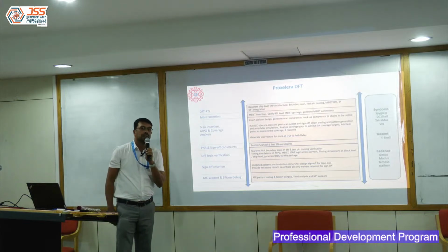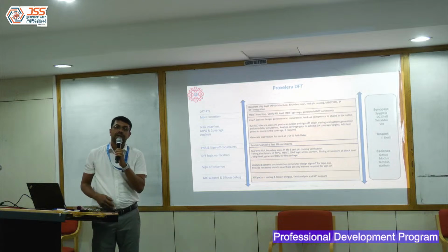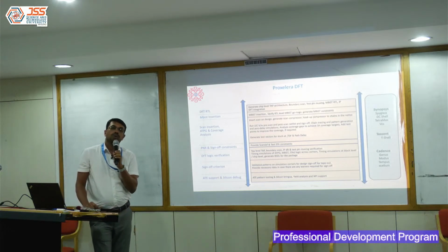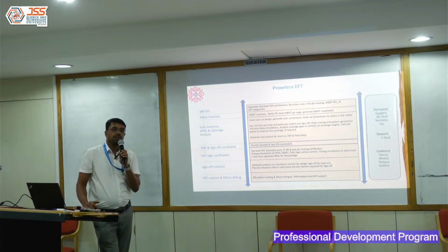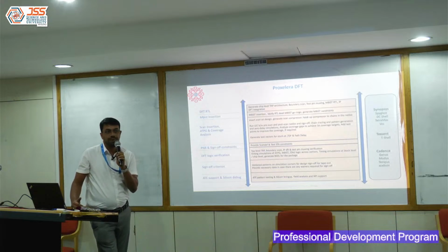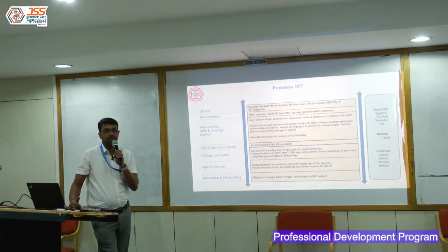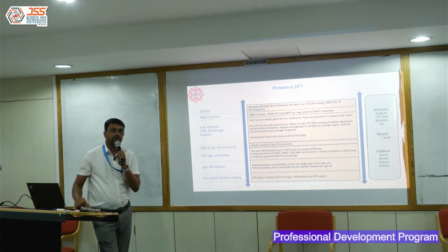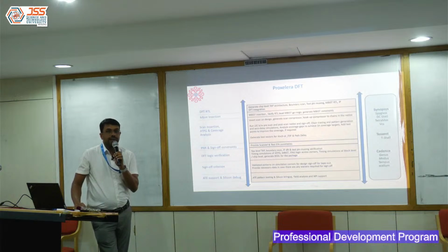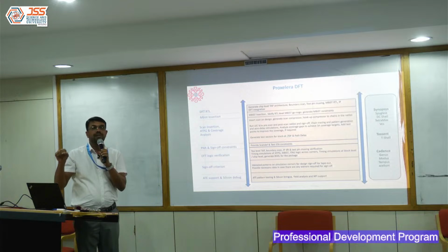Now, what is MBIST? MBIST stands for Memory Built-in Self-Test. See, today, some of the chips have close to 70% memory. If you consider the overall content of the chip, close to 70% would be memory. Now, how do you test these memories? Testing memories is a challenge. For that, we have a technique called memory BIST. So we insert a BIST engine into the design, which is going to help us test these embedded memories. When I say embedded memories, it is because these memories are deep inside your design.